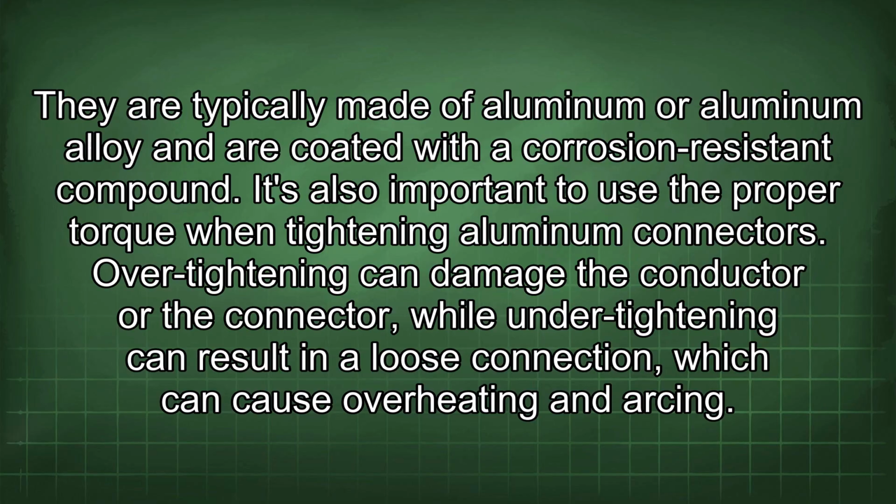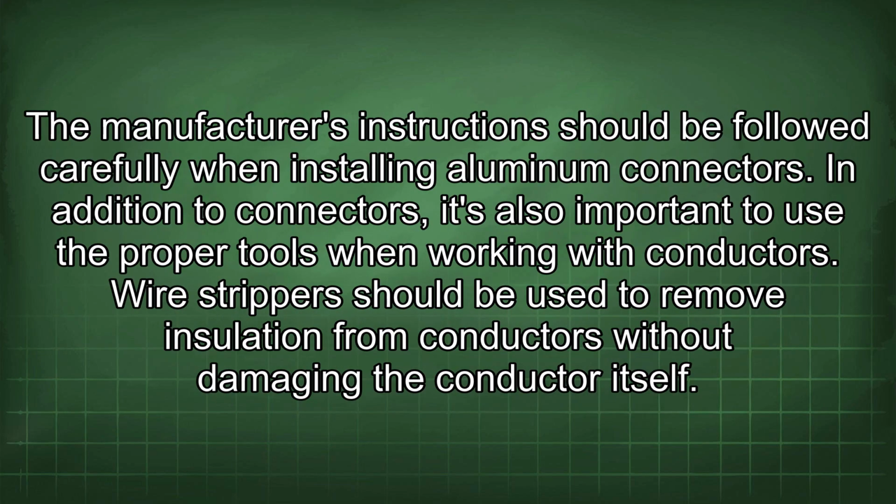It's also important to use the proper torque when tightening aluminum connectors. Over-tightening can damage the conductor or the connector, while under-tightening can result in a loose connection, which can cause overheating and arcing. The manufacturer's instructions should be followed carefully when installing aluminum connectors.